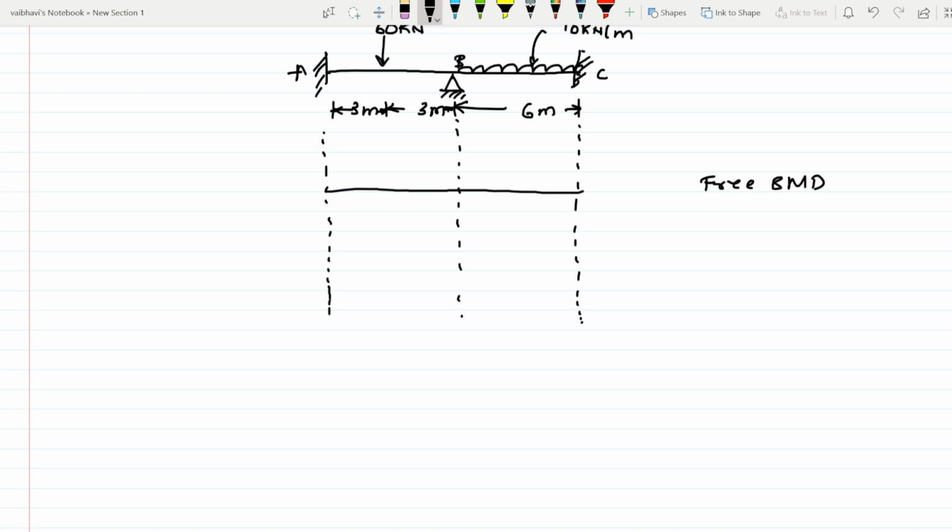First, the moment value MAB. What we have got, MAB value is minus 48.75. So minus means it is anti-clockwise, pushing the beam up like this. So we will represent it like this, 48.75. And at B, that is MBA, MBA is 37.5. Here it is 37.5.